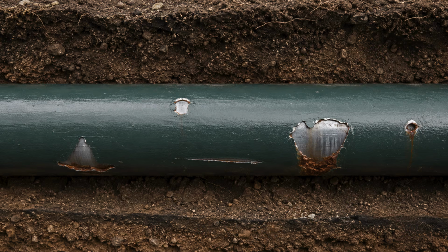That can create pitting, and pitting can penetrate the steel much faster than uniform corrosion. So, coatings are the first defense, but cathodic protection is the second defense. The coating reduces how much current is needed. Cathodic protection protects the exposed steel at coating defects. They work together. A good corrosion protection system usually needs both.